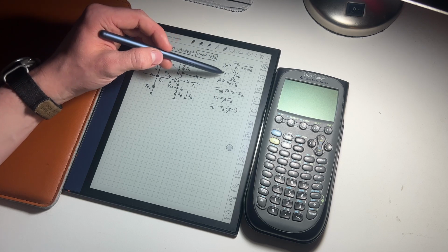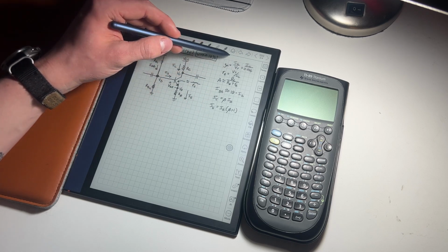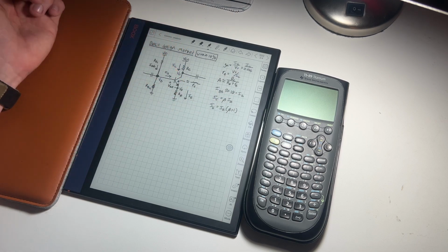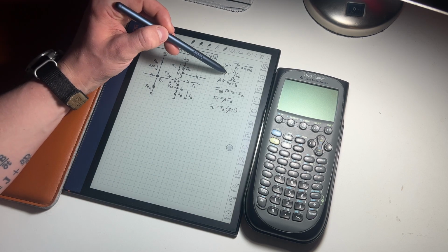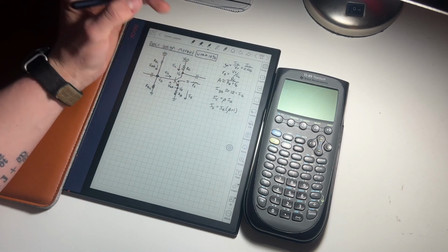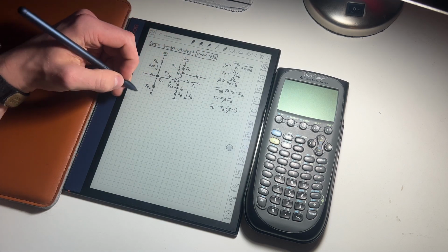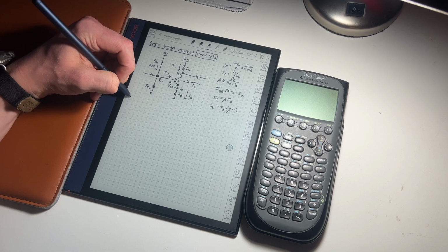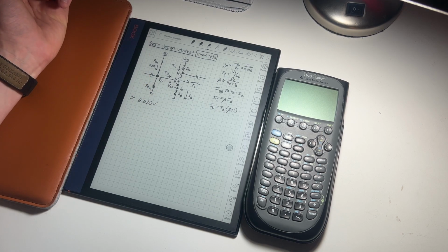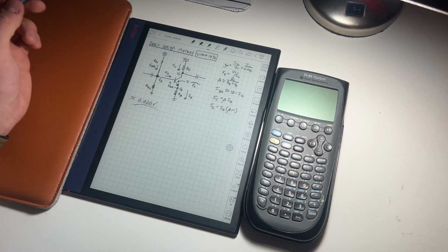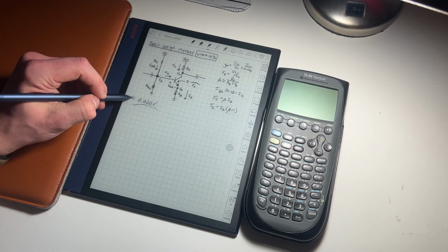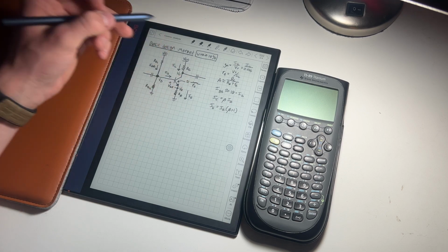On this side, I have a couple equations here. This equation you don't have to pay too much attention to, but the rest of these you should pay a little more attention to. So you can see here, I have little r sub e equals Vt over Ic. Vt is what's known as the thermal voltage, and it's typically at room temperature around 0.026 volts. That's a key number that you have to keep in mind when building these transistor amplifiers. I'm not going to go into where that is coming from in this video, but I may go into it in later videos.